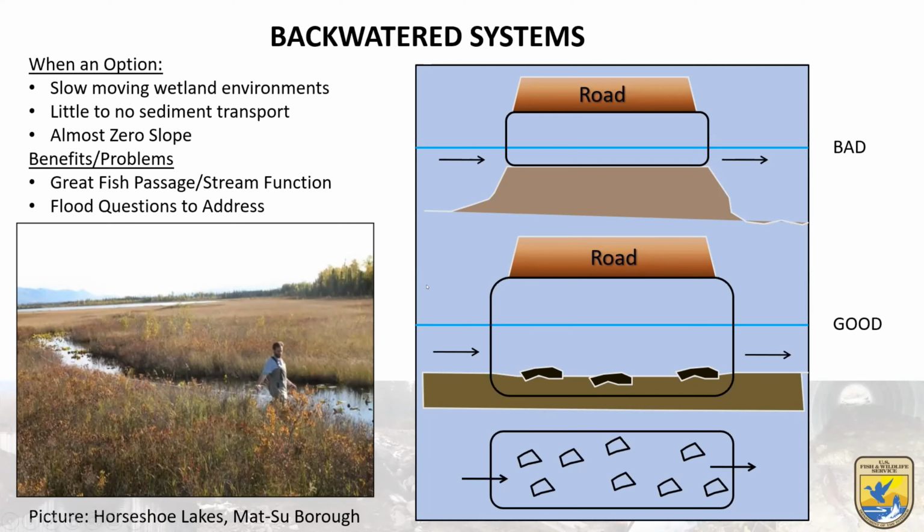You can put these in. If you're replacing an old culvert from back in the day, a lot of times they fill this channel in with sediment, and then they stick a small culvert on top. And what's bad about this is icing issues, for one. It's a lot easier to freeze, having that little bit of depth compared to the real depth of the creek itself.